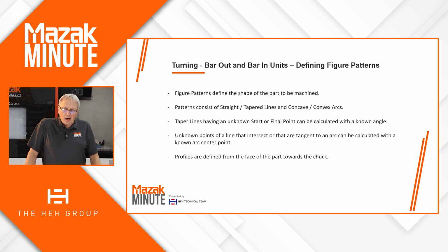As we machine in the bar out, we're going to define our shape from the front face going towards the chuck.